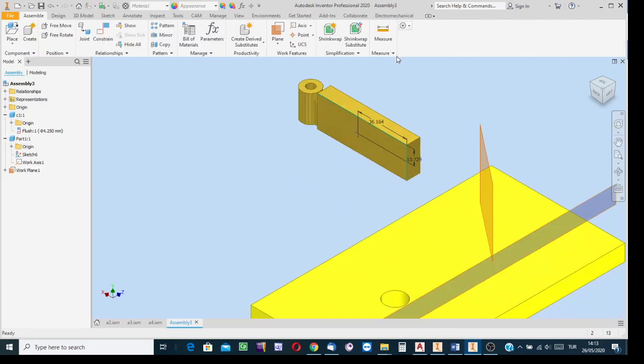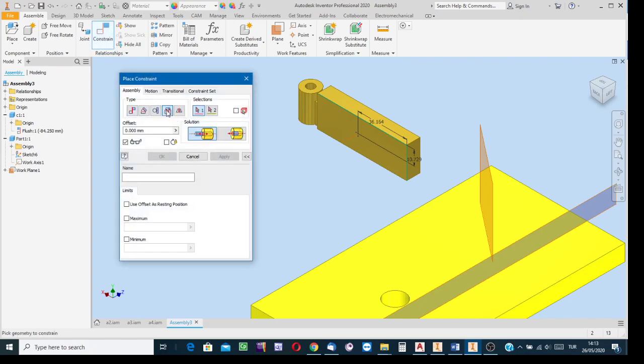Okay, and then, I am sure I clicked on the OK button, so input the constraint. Insertion type constraint. Okay, indicate the edge of this hole, indicate this work axis. Okay, and then they will be in alignment, they will position with respect to each other. Okay.